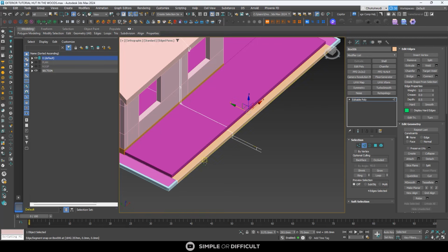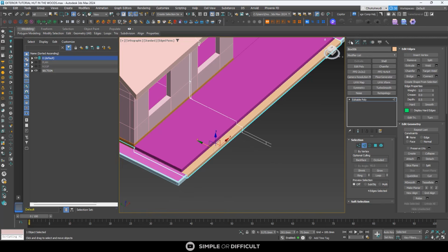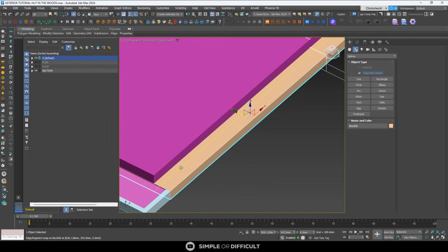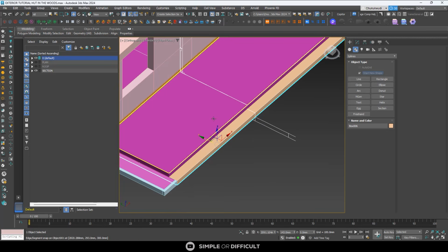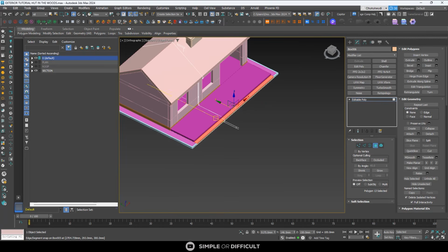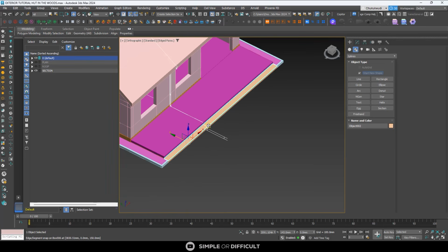Okay, because we want to create that same stuff. Detach the face, but then we want to create that floor tile alone for this front part, not the entire part. So doing this, now when I go to polygon select mode, I'm going to select only that external part. Now, when I detach as a clone, it is going to detach only that part for me, as you can see. Can you see?